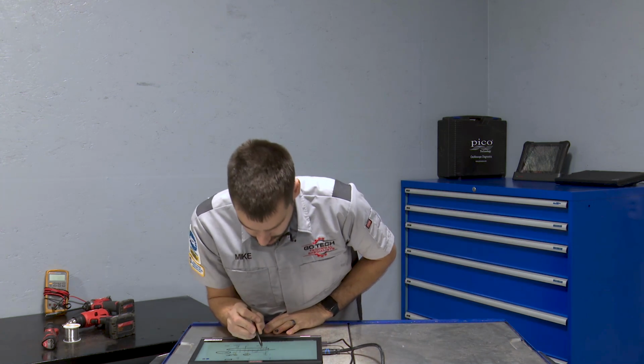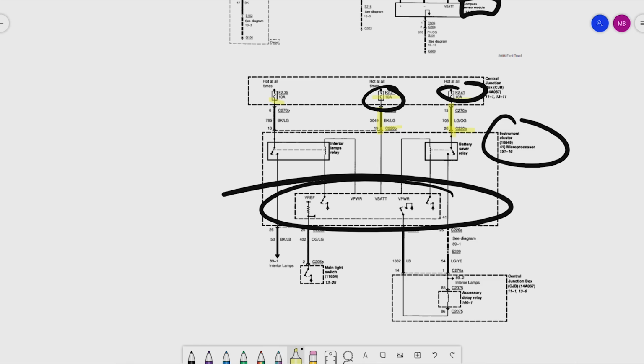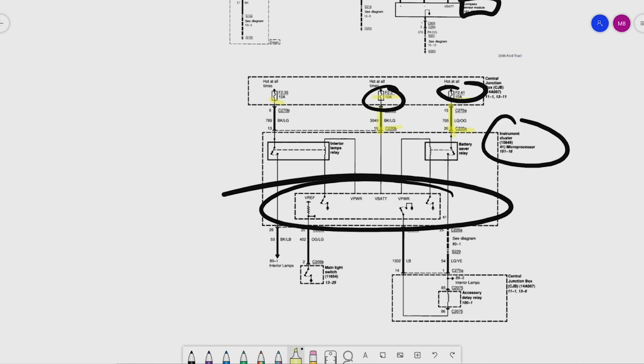This is probably where I would be getting my test light out and or a headlight bulb or whatever I want to use, something that's less than 10 amps. So really 10 amps is kind of our go-to here. Something that's less than 10 amps, probably even less than 5, would be safe. I would maybe throw a 1 amp, a 2 amp load on there, you know, a 1/4 amp test light, whatever. Basically, we're proving out that the circuit's able to flow current.